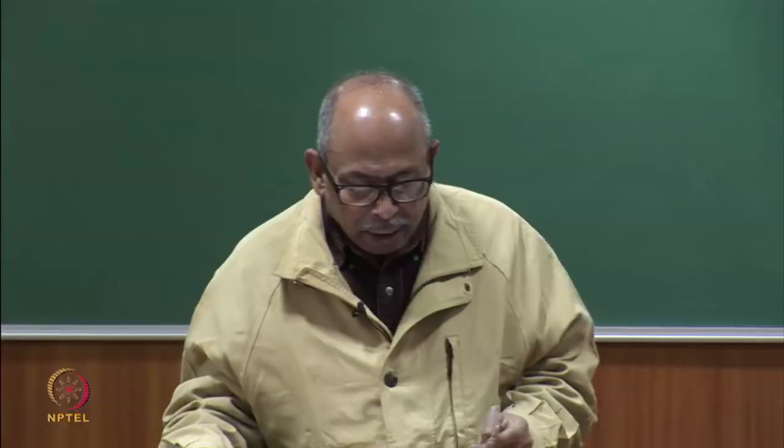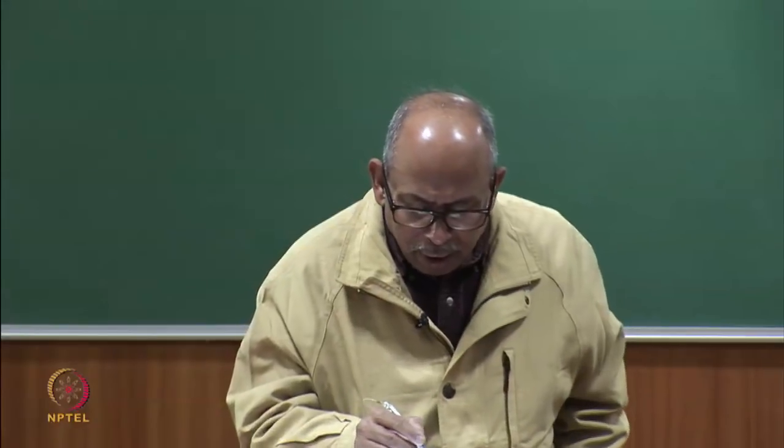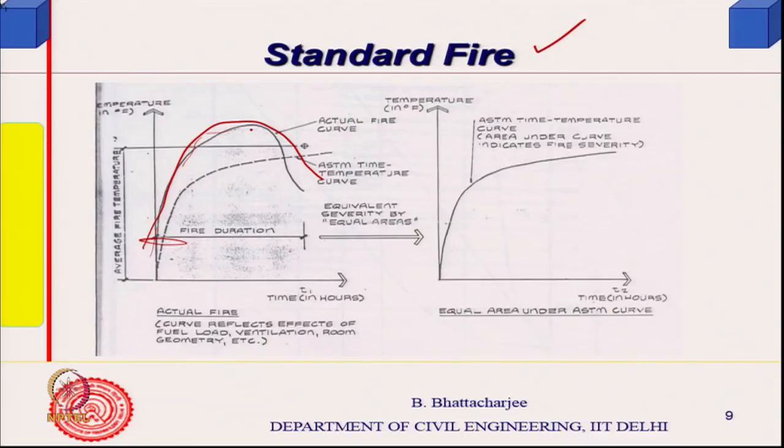So, actual fires would look something like this. Looking at the post-flashover situation particularly, before that it is in some corner and I am not so worried; it builds up, holds a steady position, then it depletes and the temperature would be somewhere there. I have some more diagrams of other fires, and we will see how they behave. Generally, you will find it something like this. They deplete after a certain period of time, beyond the duration of the fire.